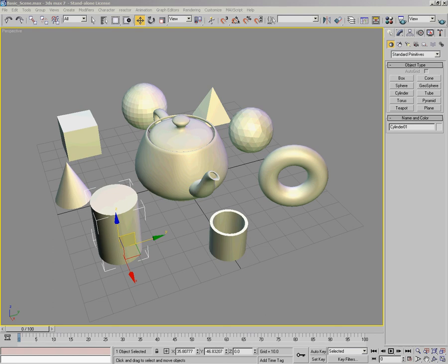Another thing of note is that currently polygons are used by all of the rendering systems out there. So even with primitives, NURBS, spline patches, or with the spline-based surfaces you get from Extrude, Lathe, and the Loft compound objects in 3ds Max, you're always going to end up with your surfaces being tessellated into a polygonal mesh when they are rendered.